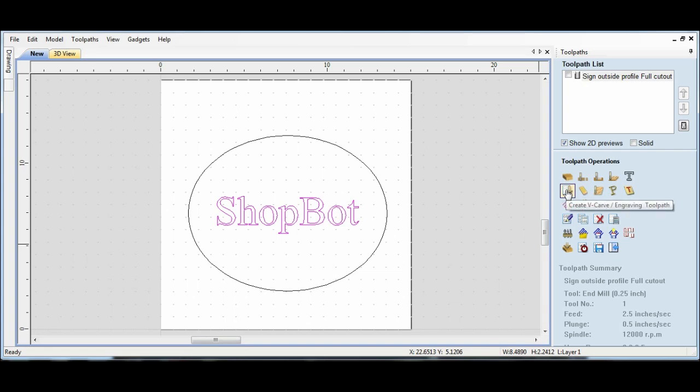And we're going to use the V-carve. V-carve is a special toolpath that, remember when we talked about 2.5D, saying it was like a calligraphy brush? So it's not just moving in the X and Y. It actually is going to plunge down a little bit in the Z direction as it's moving to create that wider line and skinnier line.